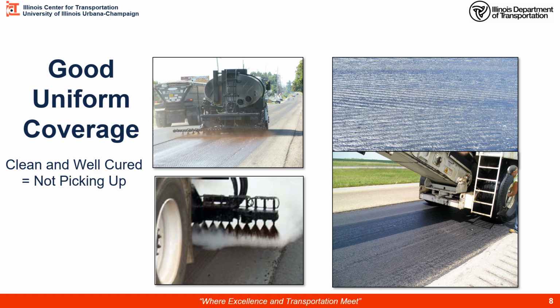It's also important that our pavement be very clean to begin with, because even if we apply it properly and allow it to cure properly, if there's a lot of dirt and debris that the tack coat is sitting on top of, it is not penetrating through that, and it will pick up on the tires. So here we have the case of the material transfer device going through a tack coat and little to no pickup. So that's what we want.